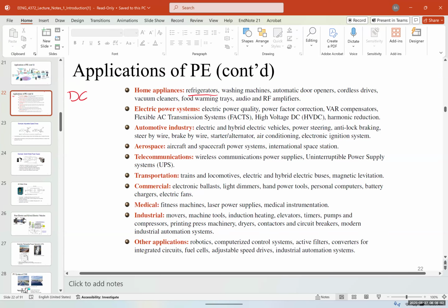But when you use an inverter or a DC, you can have precise control over the motor RPM and the torque. So instead of running 0 and 100% all the time, you can go very smoothly from 0% to 100%. If the temperature is not that high, you can run it at 20% or 30% or 50%. And again, running on and off creates a lot of stress on the motor and also wastes a lot of power.